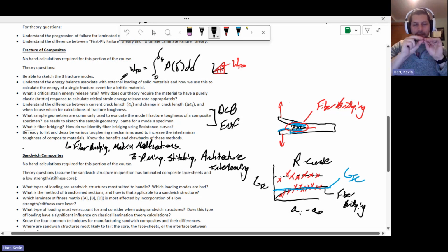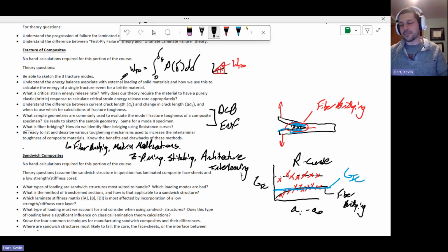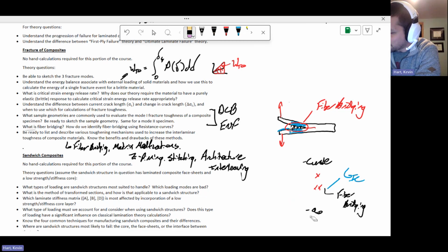Interleaving is including thin thermoplastic layers between composite layers, right? So I lay down my carbon fiber epoxy prepreg and then a very thin layer of like polyurethane, right? Another layer of carbon fiber epoxy prepreg, thin layer of polyurethane. Okay, that's interleaving. And that's one way to put tougher material at the interface between those composite layers. All right, making progress, almost there.